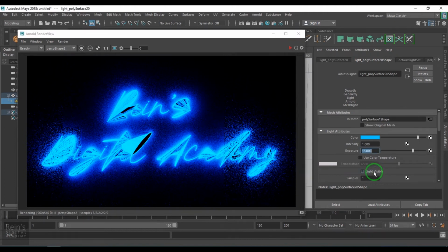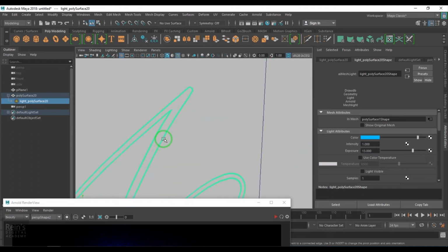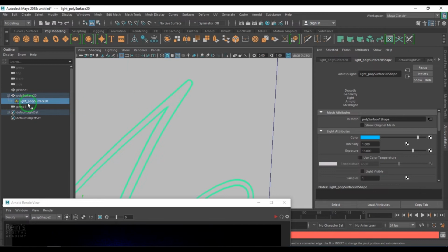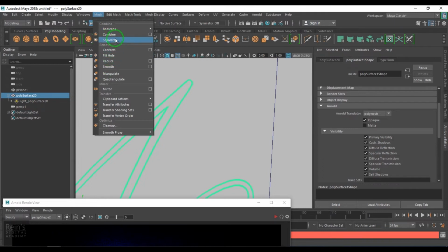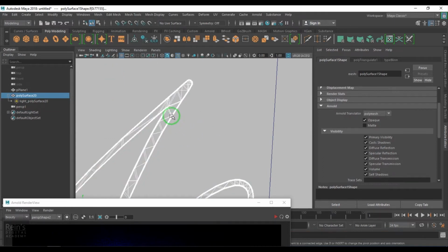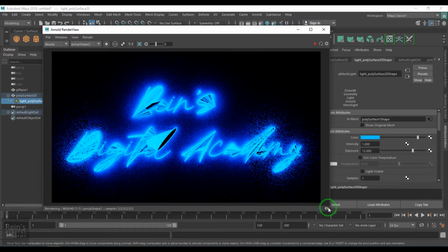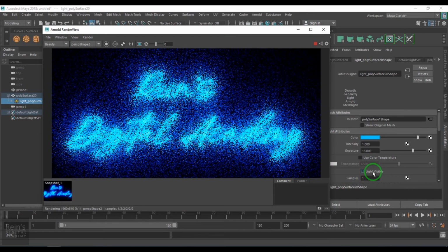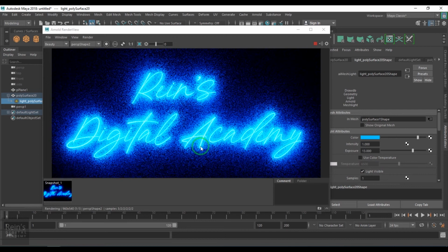So I don't prefer the light visibility initially, and I just go to the camera, and if you see here, this is the n-gon. Use this tool called Triangulate. So I think it's the geometry, and use the Triangulate option. Okay, so that gives me the triangles. Now if you see the result here, now when I render it and enable light visibility, you don't get that problem anymore.